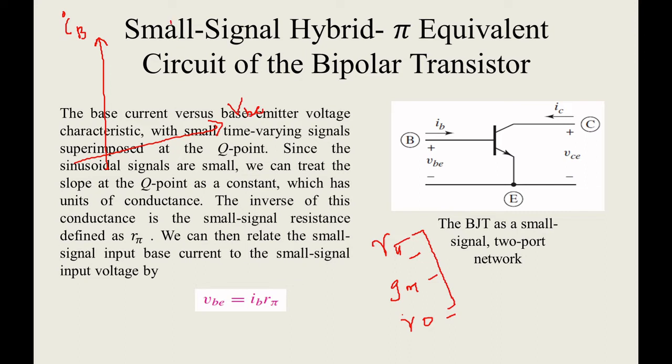So you want to see them as the performance of the input side, right? Here you are fixing the quiescent point, like IBQ, and you will have your corresponding load line plotted, with your AC superimposed on the DC point. This is your upper swing and this is the lower swing.